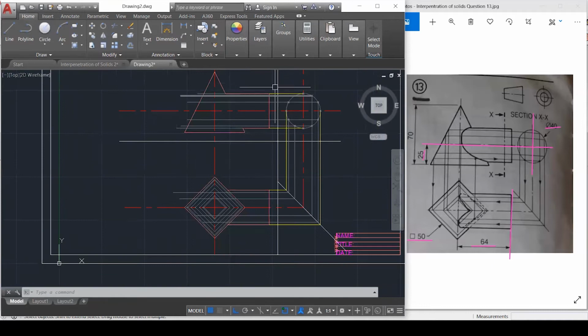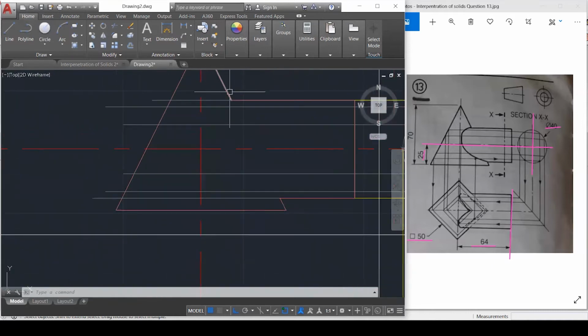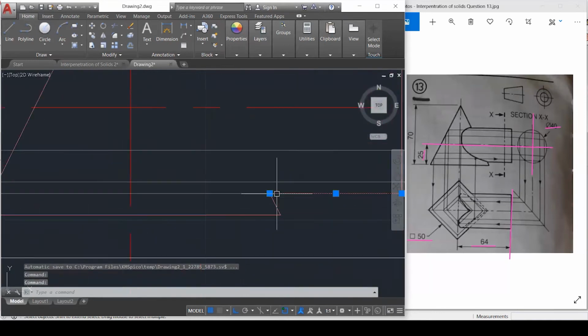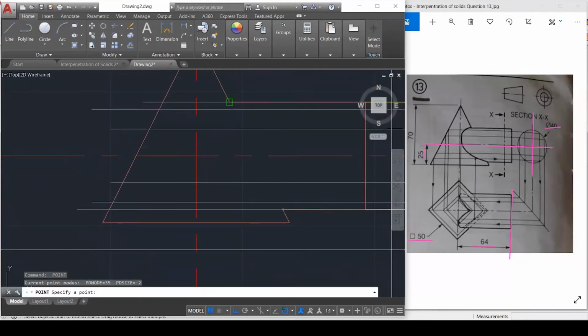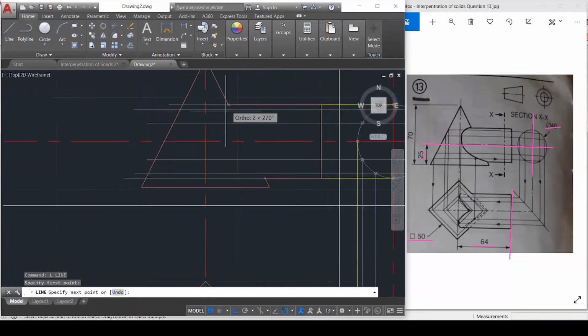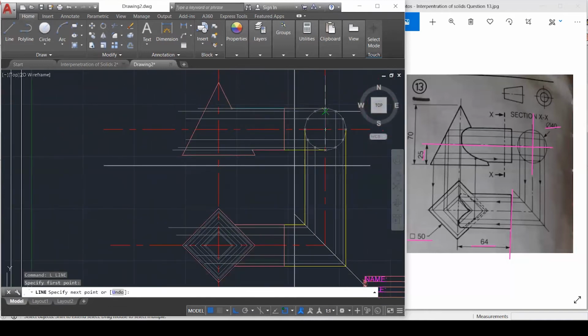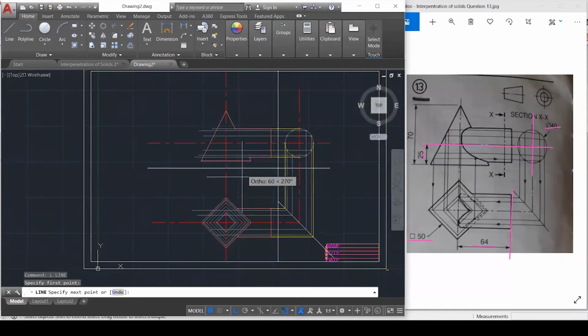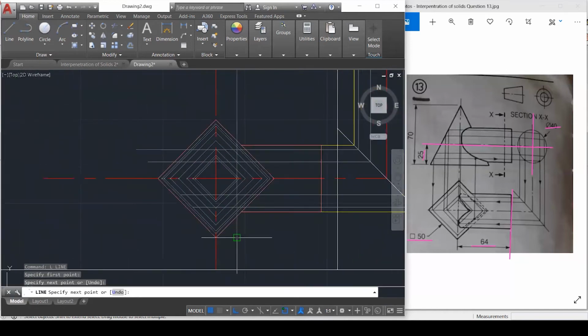So let us go with what we know. We know our top, which is the highest point, and we know our lowest point. How do we know? Because they already made an intersection right here. So I'm just going to place a point there at that intersection, and then up there. So what do I do at this time? I can safely project a line down. So this, again, is the top point here. I'm going to project a line all the way down here.